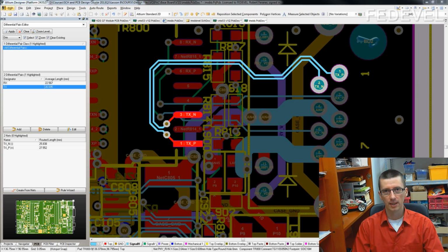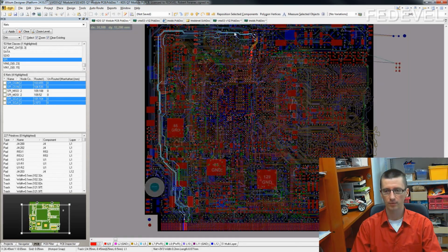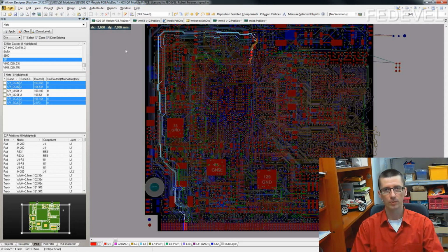When you finish this, have a look on your PCB and try to locate the unconnected interfaces and buses with longest connection, like this one. See, it goes through whole board almost. This is the kind of bus which needs to be connected now,